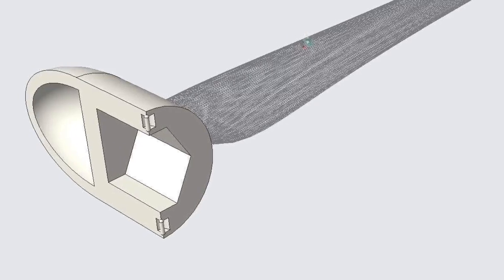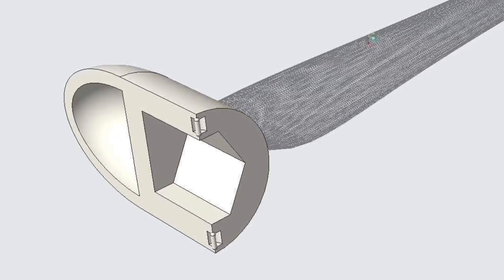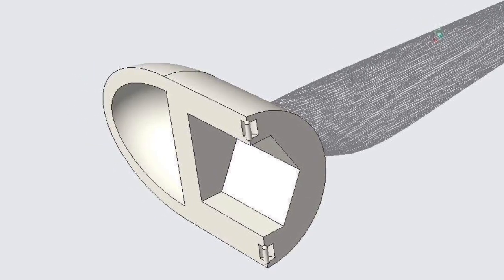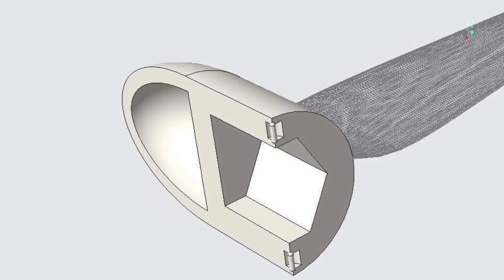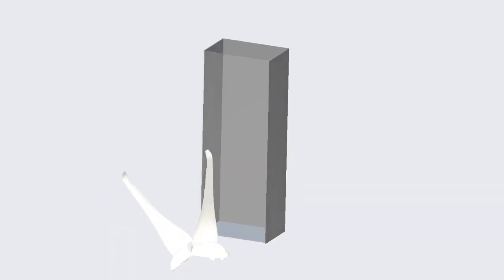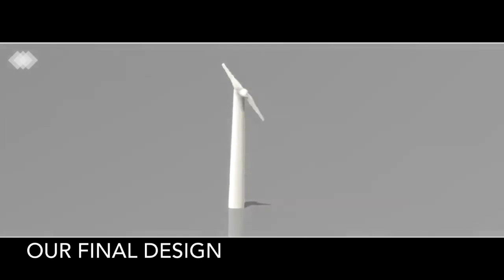We took the second concept forward, due to its comparative advantage against initial idea 1, which was deemed to be unnecessarily complicated and difficult to lock in place whilst resisting centrifugal forces. In order to perfect the tolerances for both mechanisms, small-scale prototyping was conducted. Through this, a 0.25mm tolerance between hinge surfaces was selected, and the latch design was iterated to include another arm, which limited displacement in a vertical plane, leading us to our final design.